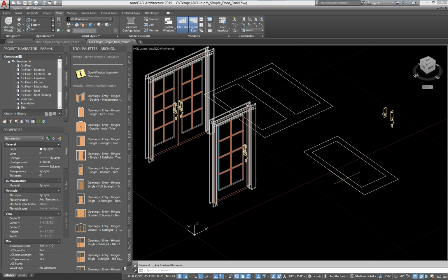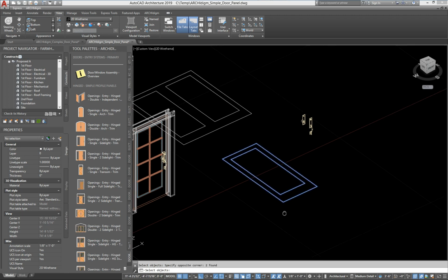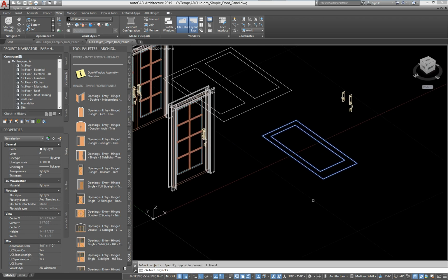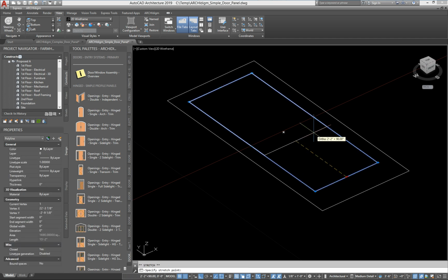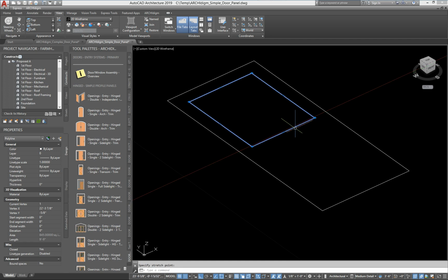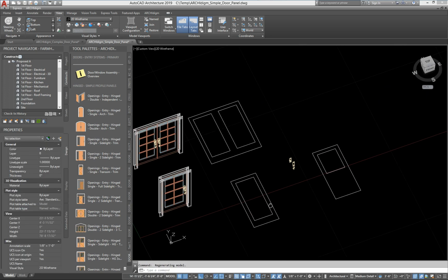And the profile basically defines the shape of the door, or I should say the door panel. It defines the shape of the door panel, and then wherever you want an opening. That's the most common use of a profile. So for example, if I take this that's being used in this door and I copy it over and I make a change to it, I bring it up about to midpoint here, and then I go to look at the top a little bit more here.